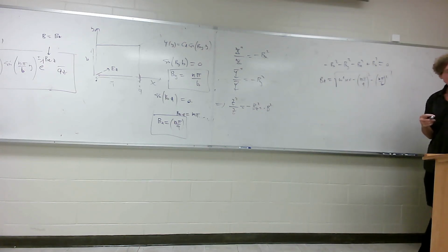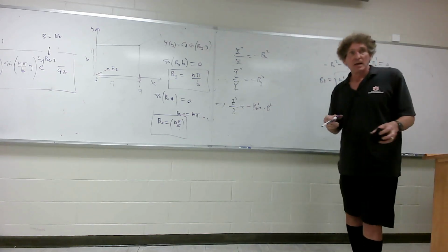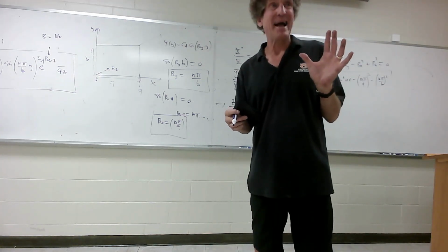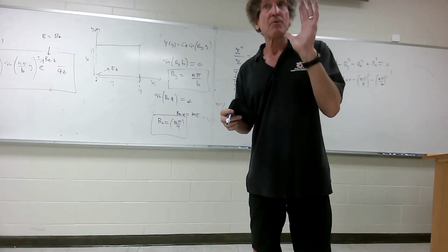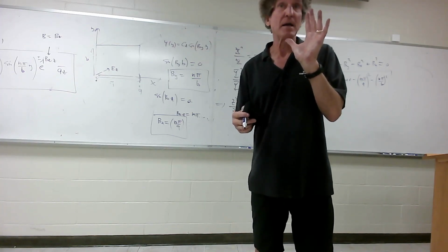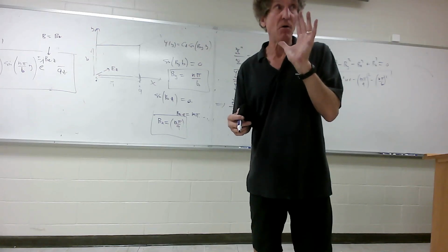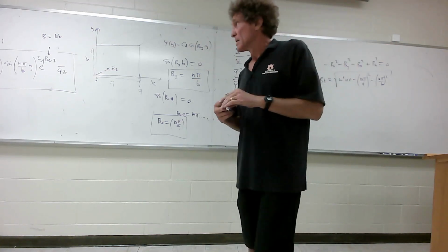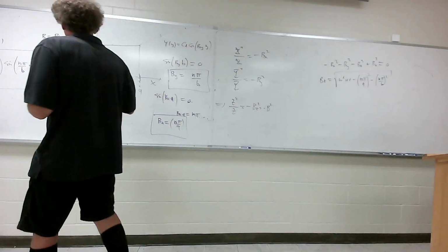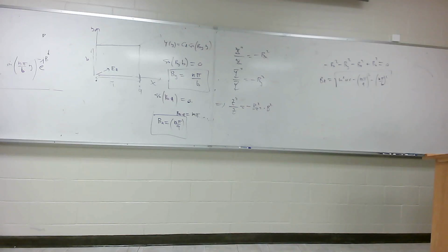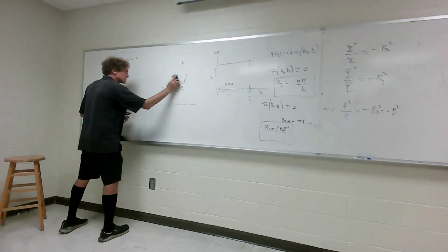Here's one really important thing. Waveguides are high-frequency pass filters. Any frequency below what's called the cutoff frequency, nothing propagates. Everything is attenuated. Y'all with me? So it will not propagate DC. How you get the cutoff frequency is the next point. And this is real important. You'll see it. I have great faith in this class. Cutoff frequency.